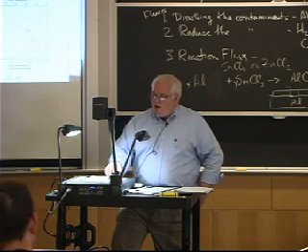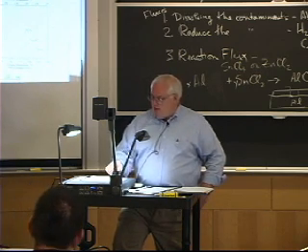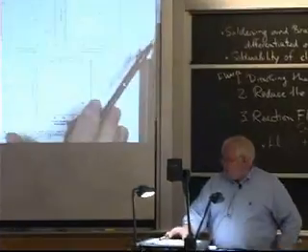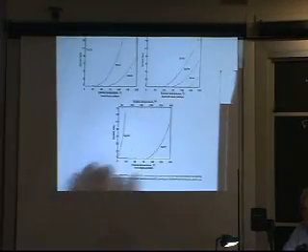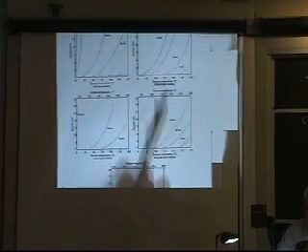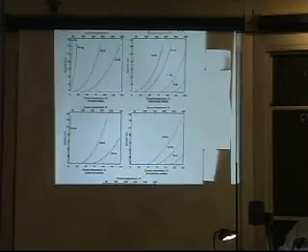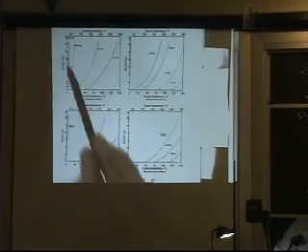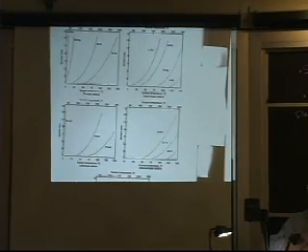Nonetheless, there is nothing better than lead tin in terms of spreadability. And you can look at all these different things. This is the silver system. Here's the bismuth system, the indium system. And they're all significantly worse than lead tin. There's a reason why we've always used lead tin for soldering. It is absolutely the best.